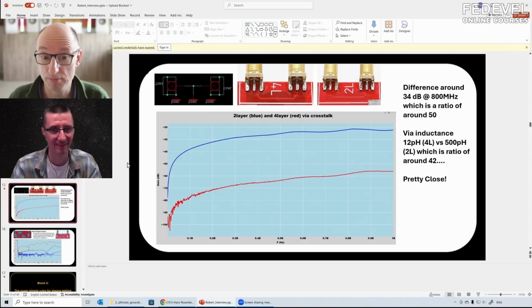So that's 10 amps. And then this via can cause so much drop that the FPGA stops working because all the timing is off, because the power supply has dropped too much. And you really have to be careful when you do things like this, and watch what you're doing.